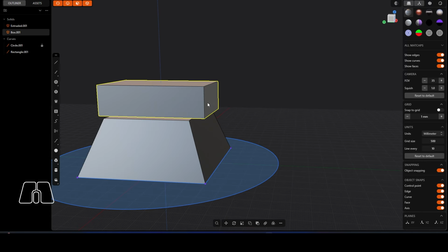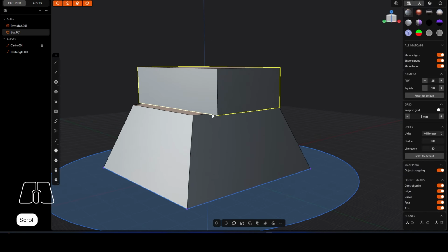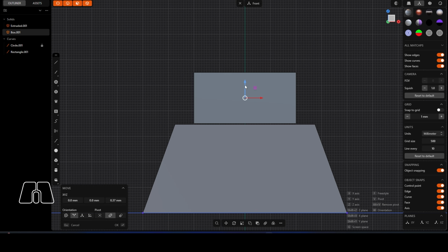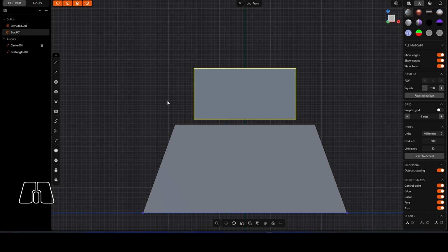The other thing that you've got to think about with turrets are the joints as well. So for this turret in particular, this is sitting quite flush here. So what we're going to do is I'm just going to move it up. It should snap here. So I can move this up a little bit. So from where it is, let's use the G key and we can move this maybe to about, I would say, 2 mil there. I think that's going to be okay.